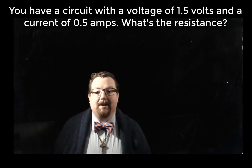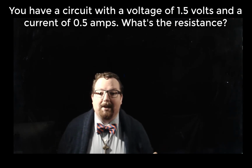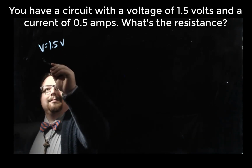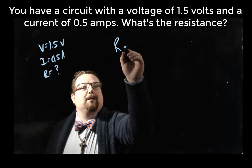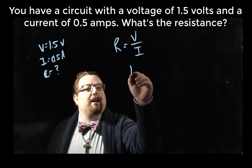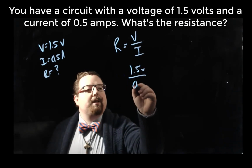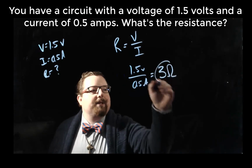Our last problem says that we have a voltage of 1.5 volts and a current of 0.5 amps. What's the resistance? So we take the R equals equation. In this case, R equals V over I. Take our 1.5 volts divided by 0.5 amps. That gets us about 3 ohms for the resistance.